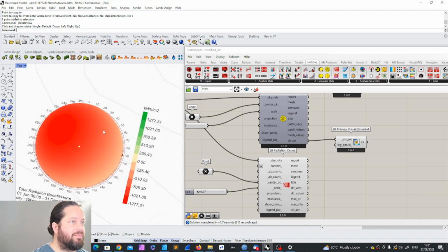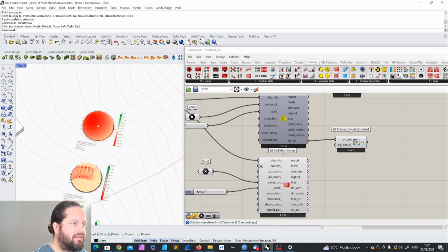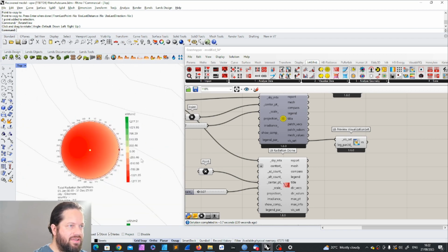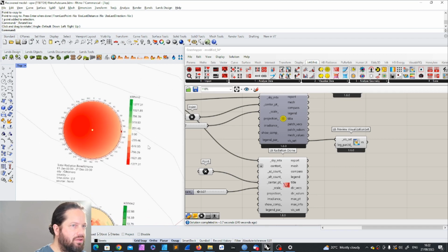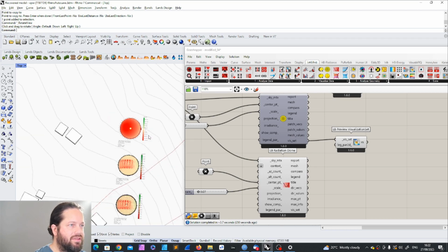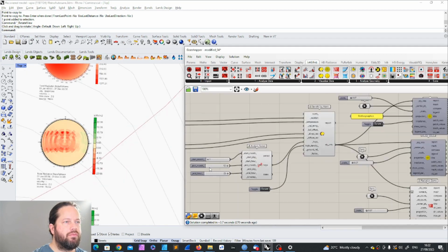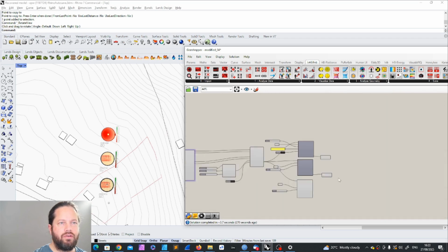So it's the reciprocal of that Sky Matrix. So imagine you have a Sky Matrix. This is the source of your light that gets projected onto an object, and then you put a hemisphere object. That's how it basically receives the sunlight. And the numbers here are as a total. And because we're using the benefit Sky Matrix, we have the positive and negative numbers, but as a total, not as an average. All right. So we're testing the whole year. Okay, that's good.